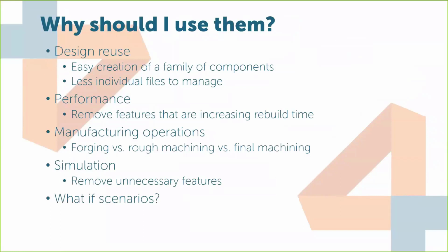Another big use of configurations is performance. If you have a part that has some really heavy features and takes a very significant amount of time to rebuild, you can suppress those features, and that'll decrease the rebuild time.